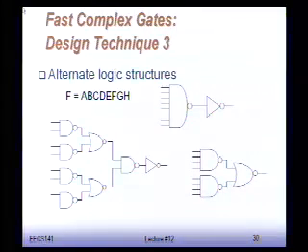The other thing you can think about is, how do I choose my logic structure, okay? If you have a 6-input logic function, you can try to do it with a 6-input logic gate. Is this 7-input even? It's 8 inputs, even better. So you can try to do it with an 8-input logic gate, or you can try to break it up in multiple stages, right?